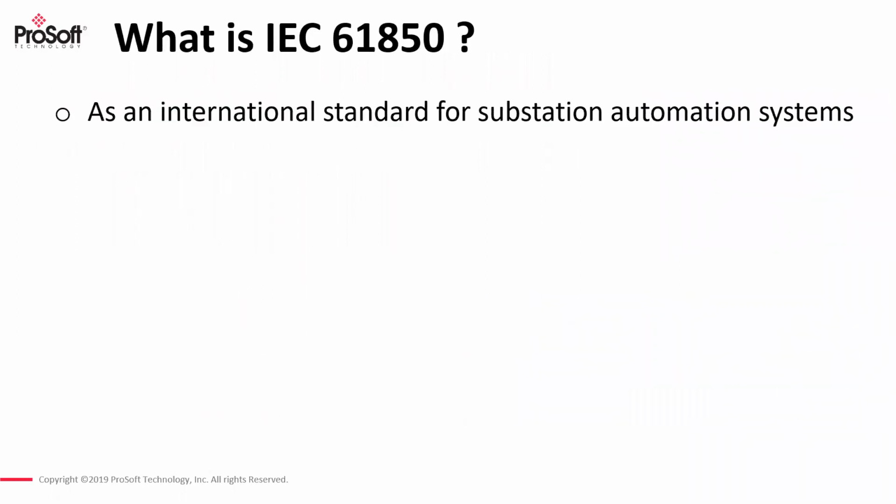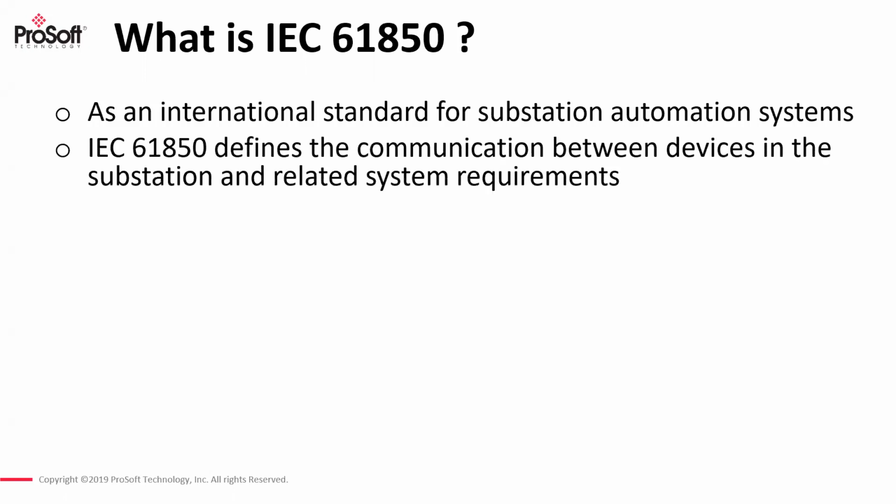So when we looked at IEC 61850, it was essentially a culmination of years of industrial standards and protocols that had failed to meet the requirements of substation applications. It's an international standard for substation automation. It defines the communication between devices in the substation and related system requirements.